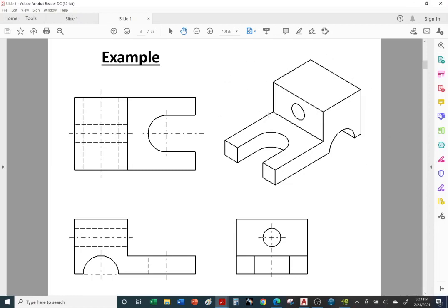Okay, so when we talked about isometric views in the previous chapter, we said imagine putting the isometric view in a glass box, or a cardboard box. So first you draw a box and then you start sketching the part. It just makes it easier. You draw a box with the height, length, and depth. You start with the simple box and then you start drawing the object lines. Once again, these are the object lines. These are around 0.50 or 0.60 millimeters in thickness. And again, your textbook will give you a range of what thickness to use on the lines.